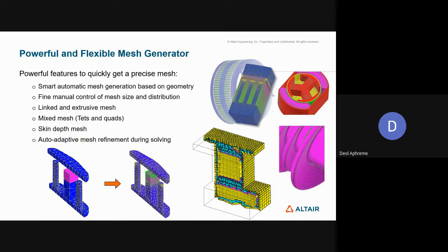So meshing is, like I said before, a very important part of finite element solving. And it is very important for your results. So if you want to get very accurate results, you definitely require a fine mesh. So when I said before, the entire geometry is cut into small prisms and tetrahedrons and quadrahedrons and whatnot, it is very important that you have it very fine in regions where maximum energy conversion is occurring.